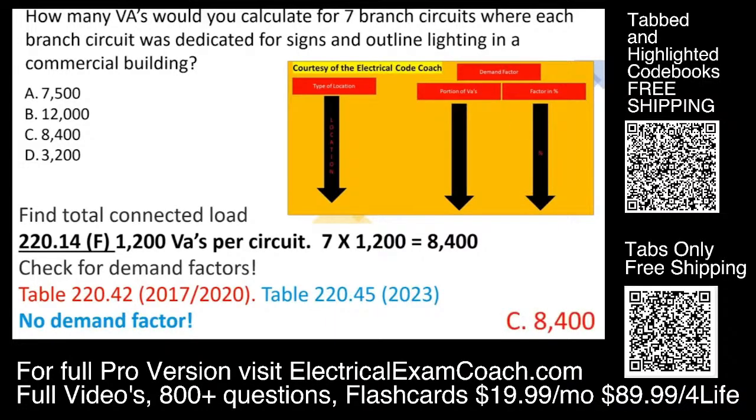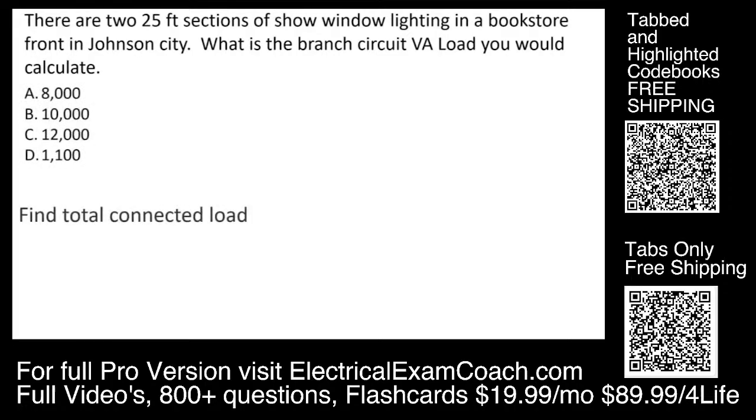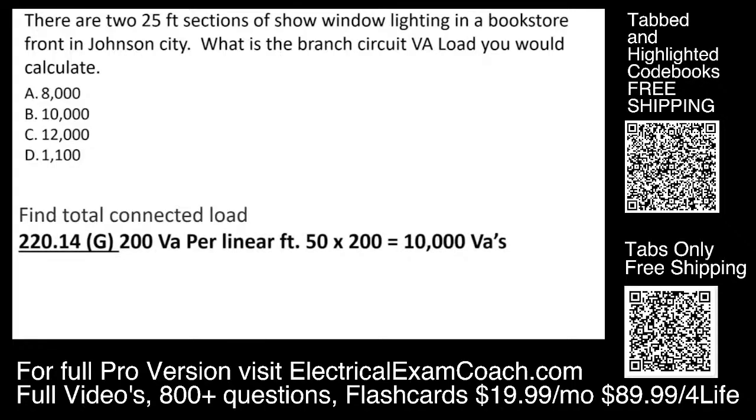Great job. There are 2 25-foot sections of show window lighting in a bookstore front in Johnson City. What is the branch circuit VA load that you would calculate? Step 1, we're going to find our total connected load. For this, we're going to head to 220.14G. It's going to let us know that it's 200 VA per linear foot. We take our 50 feet multiplied by 200 VAs each. That's going to give us a starting connected load of 10,000 VAs.